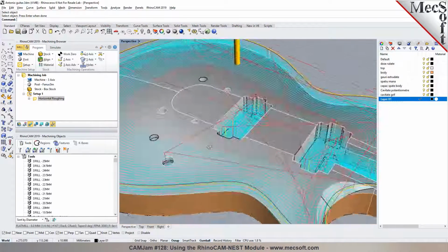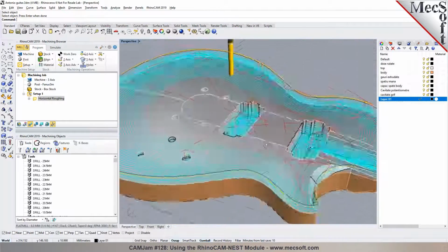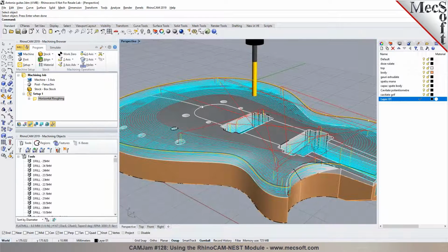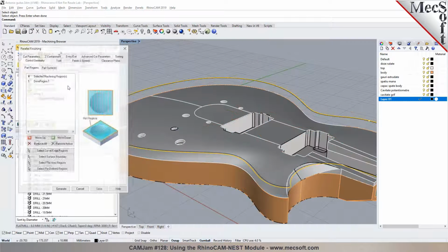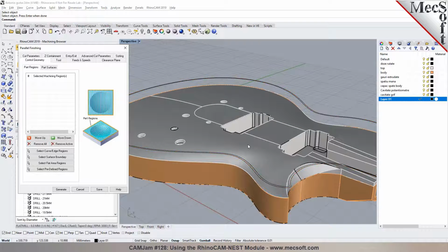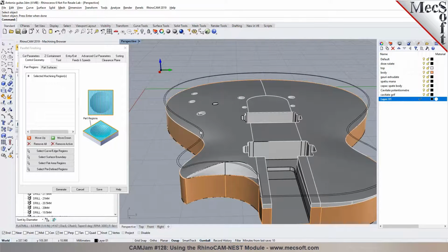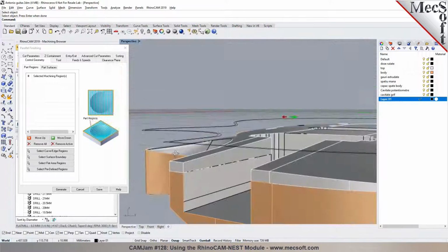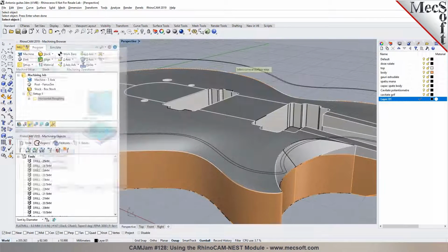Yeah, I'm not sure how you programmed it, but as you can tell here, I'm just programming it live on this demonstration, and you can see that we were able to create a roughing path. You would then want to go ahead and do a finishing operation. You could do 3-axis. You could start with a parallel finishing. And if you only want to do the top faces in here, you could just do the top faces. You can pick a boundary around the part to select the top faces, or you could do the entire thing by just selecting this boundary in here.